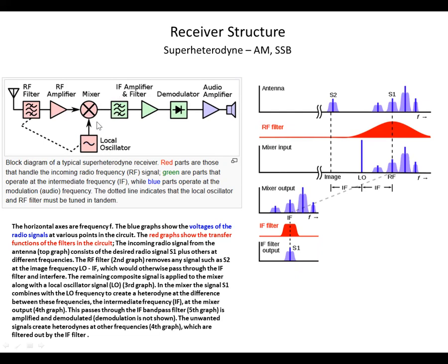The reason for that is that if you think about what we're expecting out of this radio on the front end, we want to be able to receive everything from, say, 160 meters to 6 meters, and be able to tune it, filter it, do all sorts of manipulations to it. So if you had to design a radio to do all those functions over this wide of a frequency range, it would need to be an extremely large, complex radio, because all the values that you're using for your filters and your amplifiers and things like that are sensitive to the frequency. So depending on what frequency range you're in, you'd have to have different components.